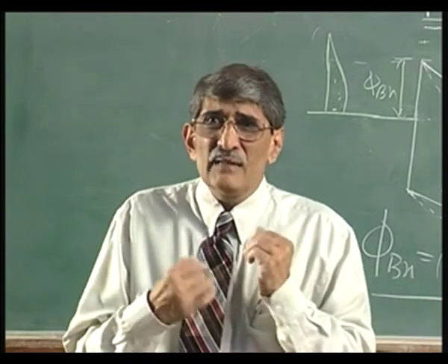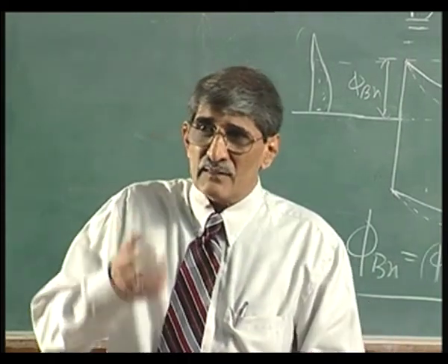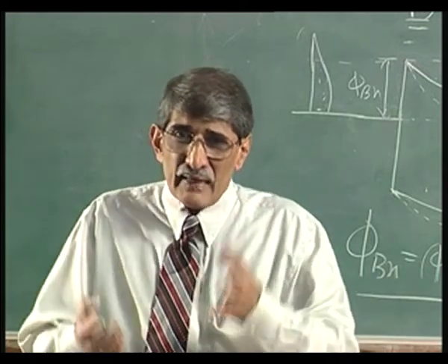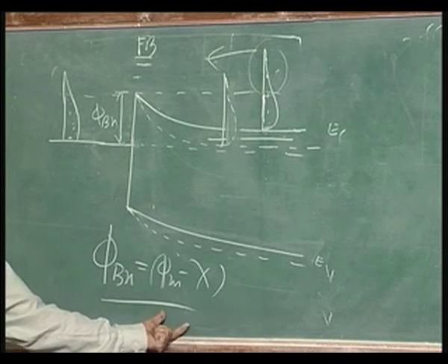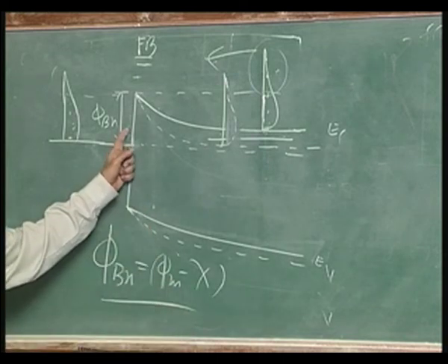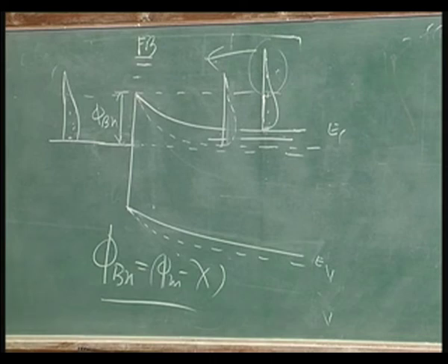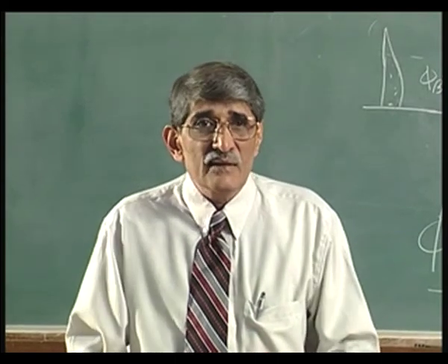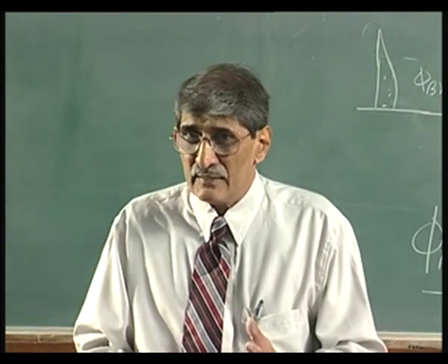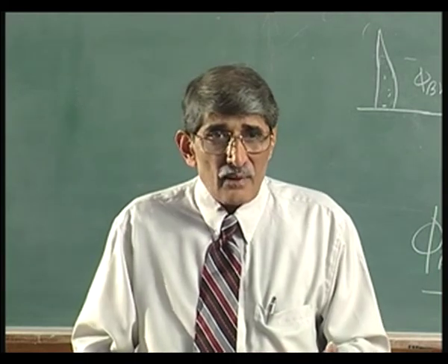Okay. So, generally people say the phi m of the metal must be large compared to phi s of the semiconductor. What matters is the difference here between phi m and chi. Smaller it is, closer it is to the ohmic contact. Larger it is, closer it is to the rectifying contact. So, we look forward to seeing what type of impact these metals really have in making ohmic contact and rectifying contact. We also will see in the case of p-type material what will happen.